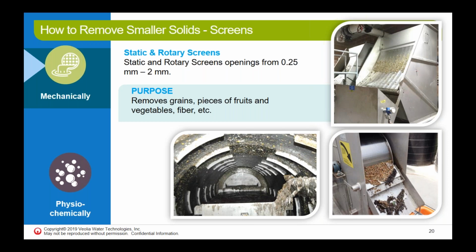So these types of separation devices do not require as much maintenance, and we're talking about static and rotary screens. In the case of the slide heel static screens, we're applying the water flow against the mechanical barrier, and we're using gravity forces to let the coarse material slide into the hopper, so the treated water proceeds forward and the coarse separated material is accumulating within the hopper.